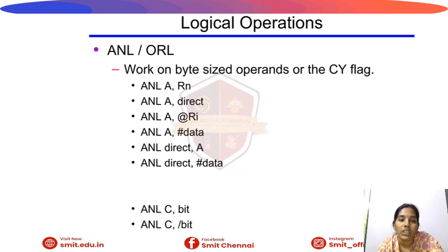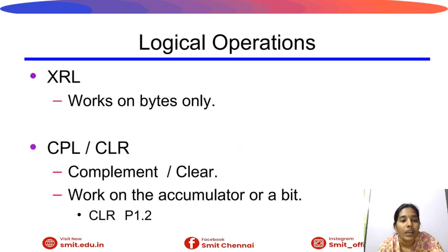Next are the logical instructions. AND, OR or XOR operations are done using these instructions. ANL is the instruction used for the AND operation, ORL is used for the OR operation, XRL is used for the exclusive OR operation, CPL is the complement, and CLR is the clear instruction.